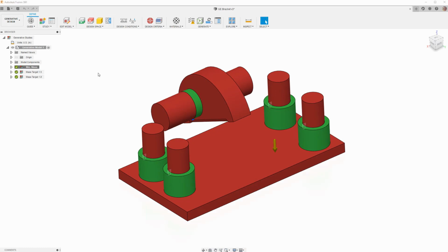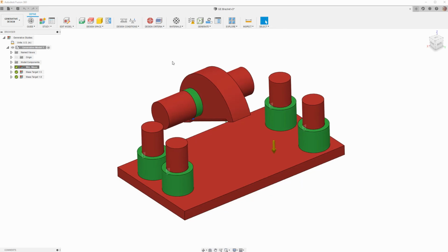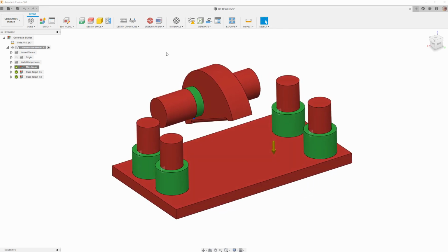So first things first, on the left-hand side, you can see in the upper corner, we're just going to go left to right and run through basically the setup of one of these, just so everyone has a full understanding of what all this stuff is. In this first pull down, you can see that there's study settings. This is where we control the synthesis resolution, basically the level of detail of the generative design study. If you've ever done any structural analysis or FEA, CFD analysis, anything with a mesh, this is the mesh. And we'll get into this a little bit later.